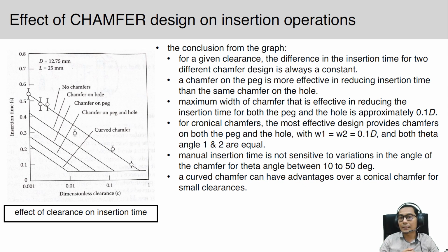The manual insertion time is not sensitive to variations in the angle of the chamfer for theta angle between 10 and 50 degrees.